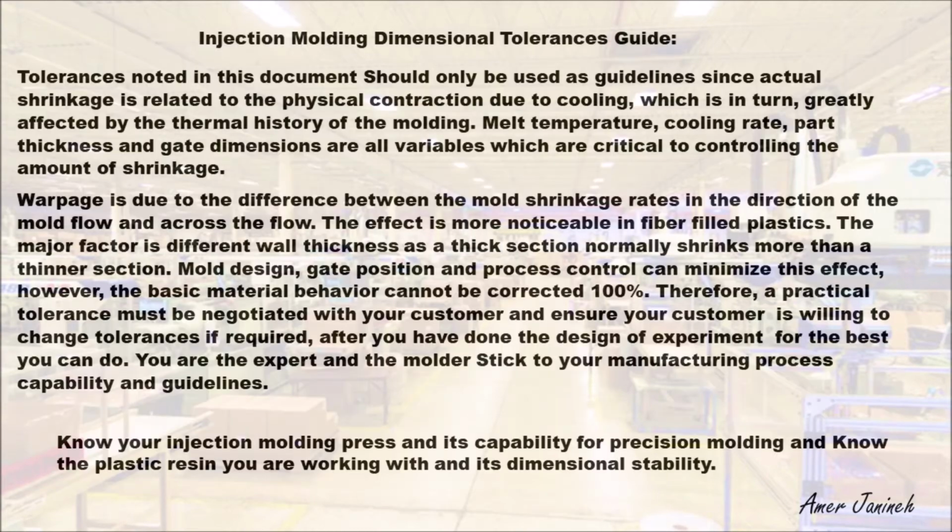The following are my recommendations for dimensional tolerances based on the industry standard for injection molding and my experience. Tolerances noted in this document should only be used as guidelines since actual shrinkage is related to the physical contraction due to cooling, which is, in turn, greatly affected by the thermal history of the molding. Melt temperature, cooling rate, part thickness, and gate dimensions are all variables which are critical to controlling the amount of